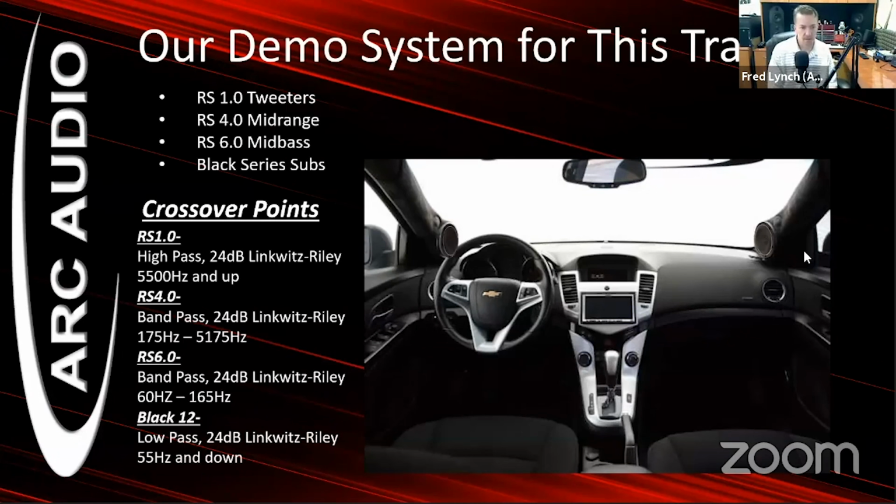Crossover points that we're using for the system: the RS 1.0s are high pass 24 dB Linkwitz Riley at 5,500 hertz and up. RS 4.0 is a band pass crossover at 24 dB from 175 to 5175. We have a slight underlap on there, and that is because of where some of the natural gain is in this particular vehicle.